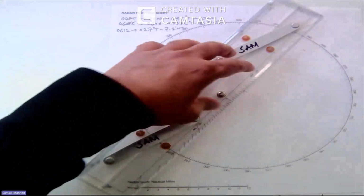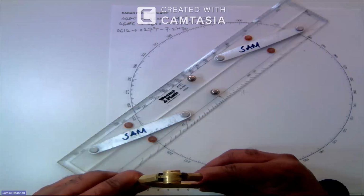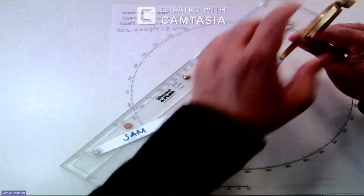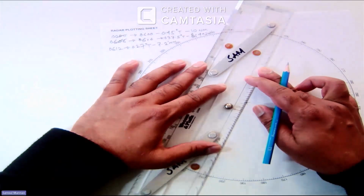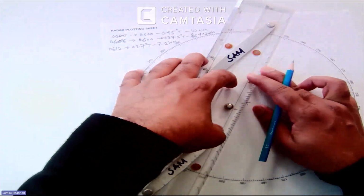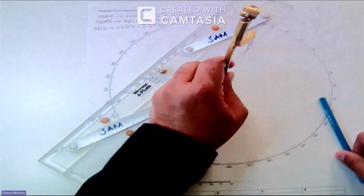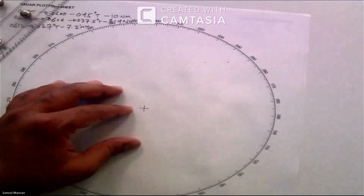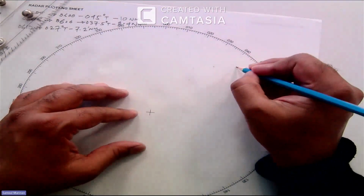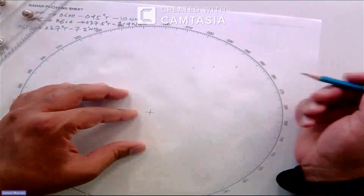Now I am taking the second range and bearing. My second bearing is 037, and I am taking 8.4 nautical miles from the radar plotting sheet, and I have pointed that one. Then the third range and bearing, my third bearing is 027 degrees true, and my range is 7.2 nautical miles. So I have got my three ranges and bearings. Now I am marking those in the radar plotting sheet.